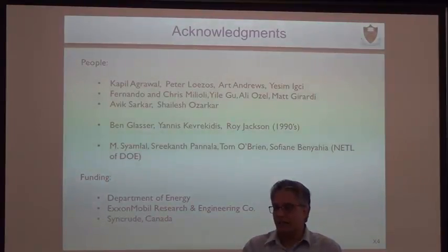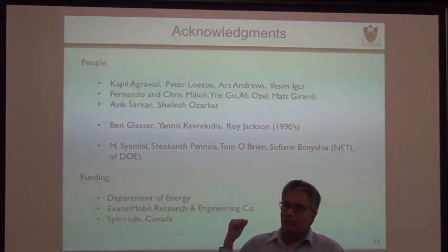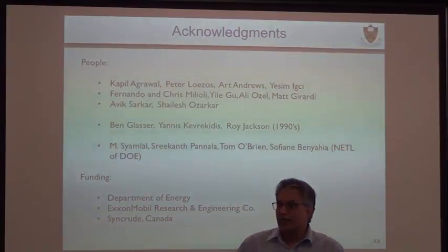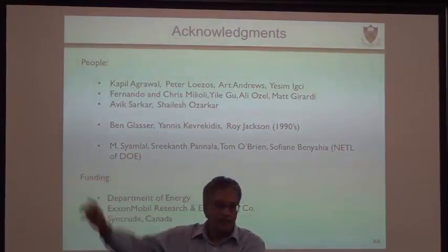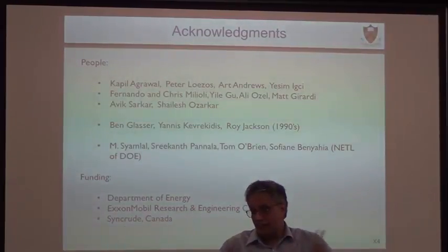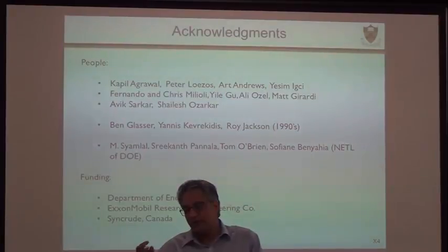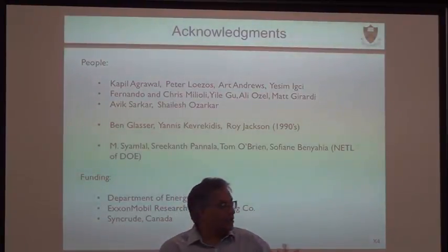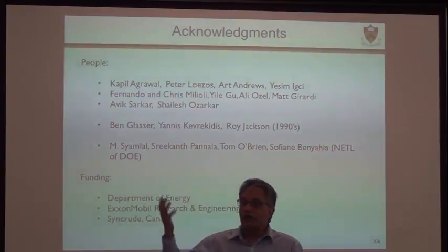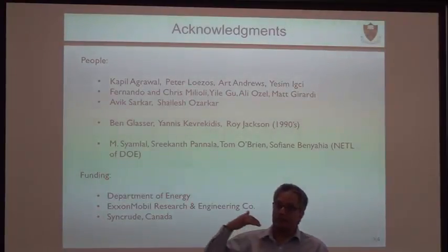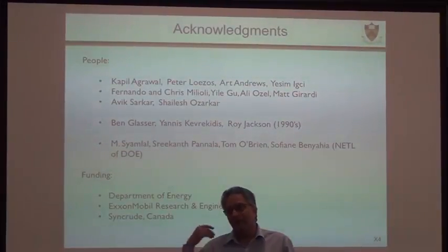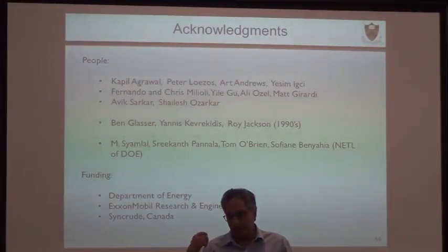It depends on the objectives of the problem. Here, the objective is that people who do large-scale reactors want to worry about the large-scale coherent structure. If all the particles in the reactor are on one side and all the gas is going on the right side, we want to know that, because that means they are not contacting each other. They are not worried so much about an 8-particle or 10-particle cluster. They are worried about whether the gas and particles are seeing each other or not. When you look at macro-scale inhomogeneities, which cause the biggest loss of productivity, then it makes sense to go in this fashion.